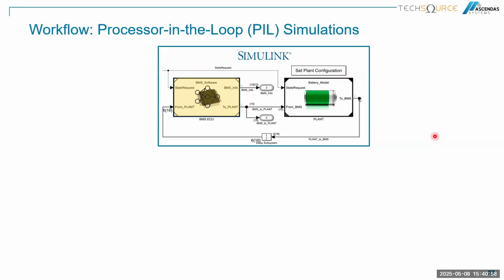And this one is one of the examples: after you deploy to C code already, and deploy to the MCU already, you need to finalize by validating your embedded code using PIL simulation, generated to match with your embedded target. For example, you use an ARM Cortex, or you use an NXP board.